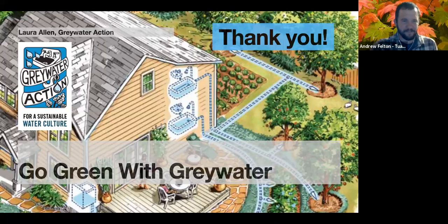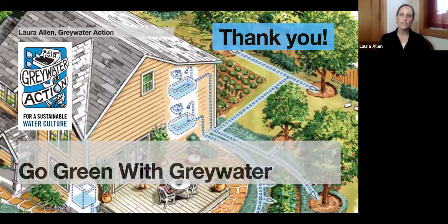No worries. When you're doing those mulch basins, will any wood chips work, or do they need to be a hardwood? Any wood chips would work. The bigger the chip and the harder it is, the longer it will last. Over time, especially when you're adding moisture, these wood chips will decompose. Once they've decomposed, they'll turn into really nice organic matter that you're adding into your landscape, but they won't filter as well and they won't infiltrate as quickly. So once a year, you'll check on your basin. If you look down and you see soil and not wood chips, then you need to remove that soil and add fresh wood chips. Some people use very fine chips, and that happens much quicker than with bigger or harder wood chips. So it's just a maintenance question.